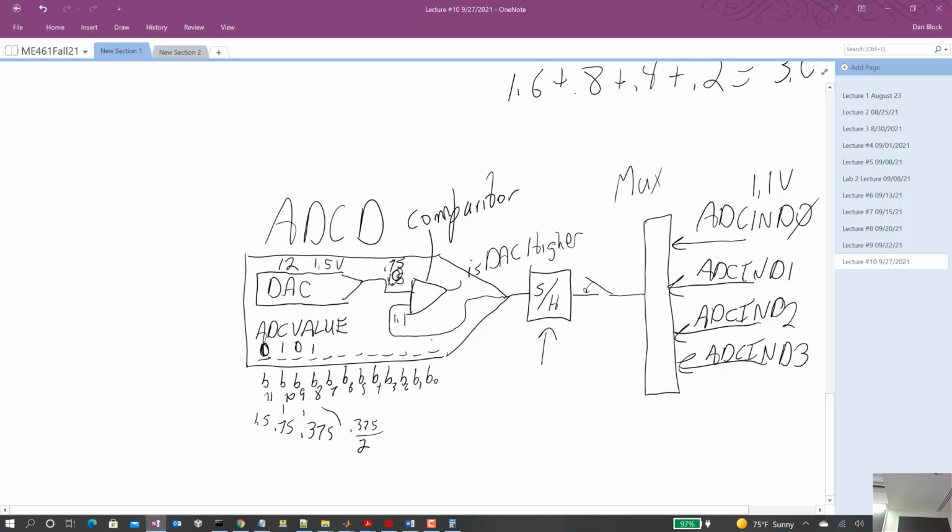I've played around with this ADC, and I found it to work pretty darn well, being as fast or faster than 500 nanoseconds. So that's pretty darn fast. But remember, an instruction on our CPU happens every 5 nanoseconds, doesn't it? So you can't just say ADC convert and then go read its value the next instruction. Okay? We have to say convert, and then what are we going to wait for to know that its conversion's done? What do you guys think?